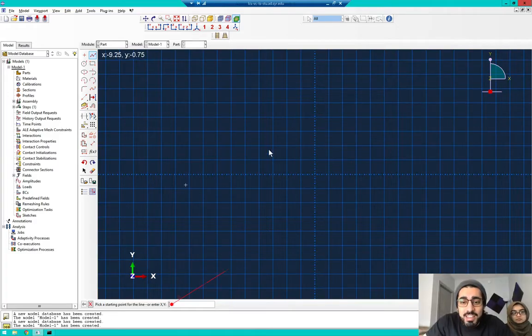So we can click here on the point. I'm going to start from the origin. You can actually type on the keyboard. You can either click on the origin, or you can type it here. They tell you X and Y separated by a comma. 0, 0. Enter. Good.